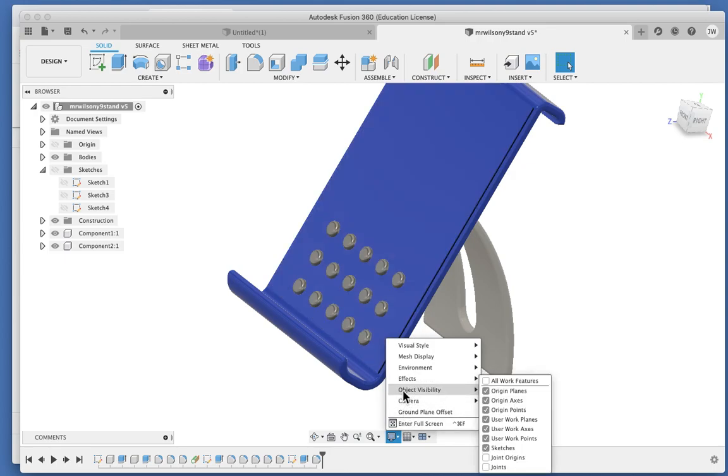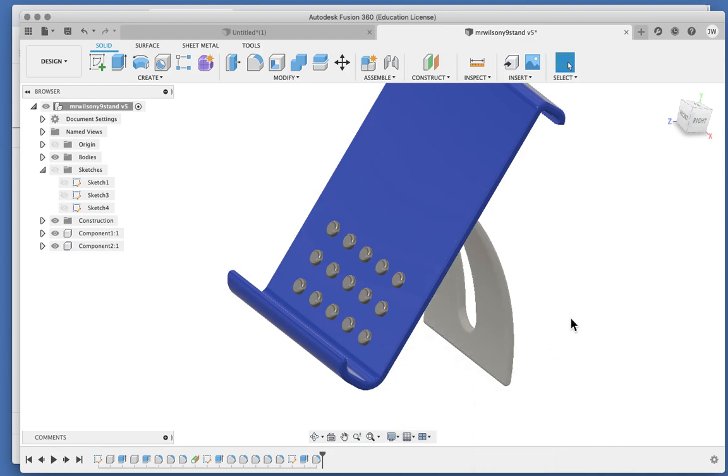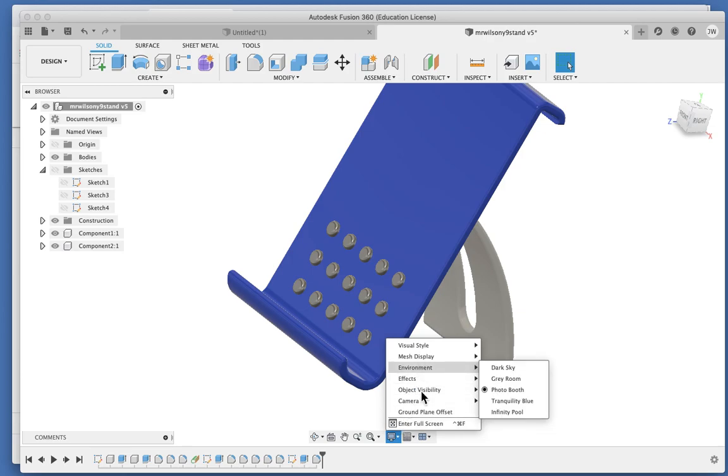And if you've got any other little icons or marks on your drawing, maybe things like, for example, if you've used the J tool to join things, you may have what look like little Lego blocks in positions where you've done joins. It's just a little icon. Well, you can come in and you can untick all of those things in here. You could untick everything there if you weren't sure which was which. So that's in your display and settings, and it's known as object visibility. Now, if I tick mine on and off, actually there's nothing that is there to remove anyway.